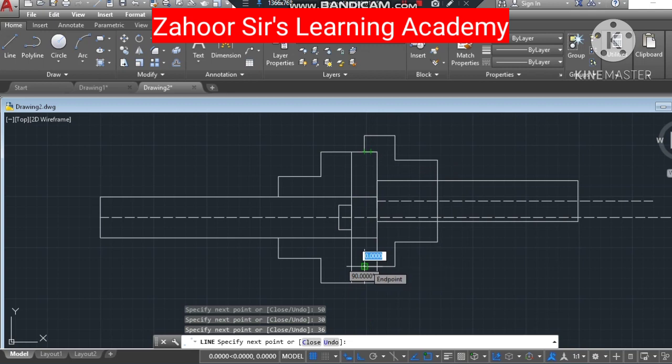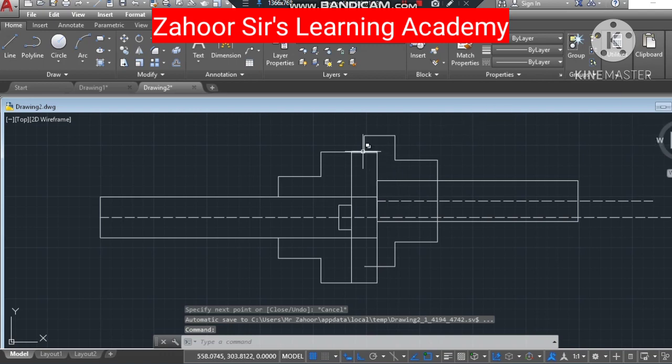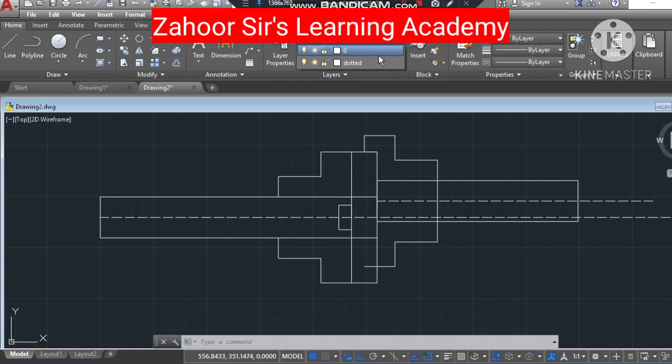Initially I will drop it, and I will press escape. Then I'll join these 2 points with a dotted line. So I will go back to the layer to keep a dotted line there. Now I can join these 2 points, to be connected with a dotted line.